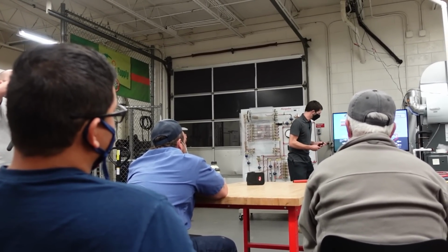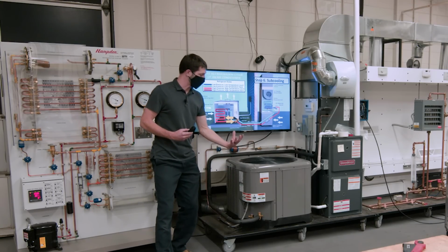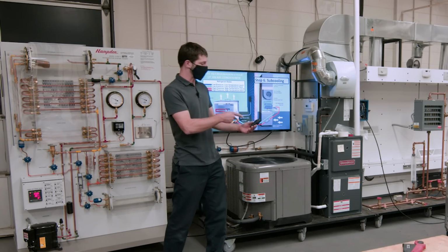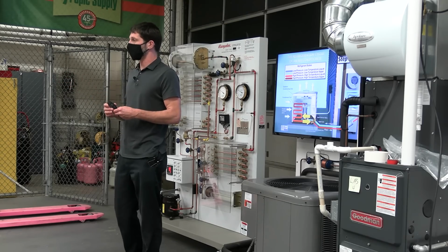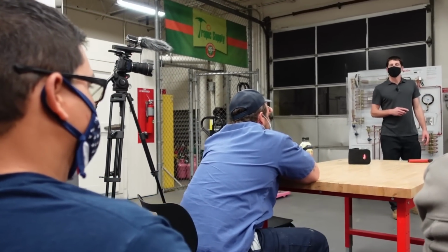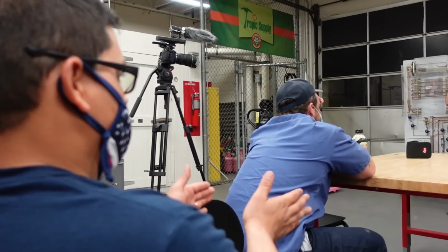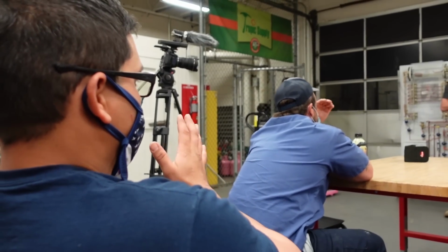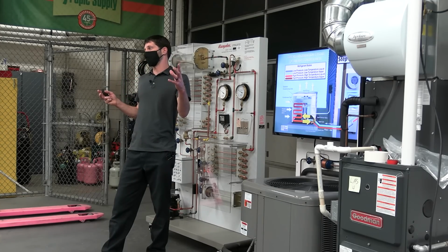So some manufacturers give you a chart where you open up this shroud and it tells you, based on the temperature outside, what the subcooling should be, the target subcooling. Does that answer the question? Yes, yes. So based on whatever they give me, it doesn't matter. It's not going to be real far away from that.